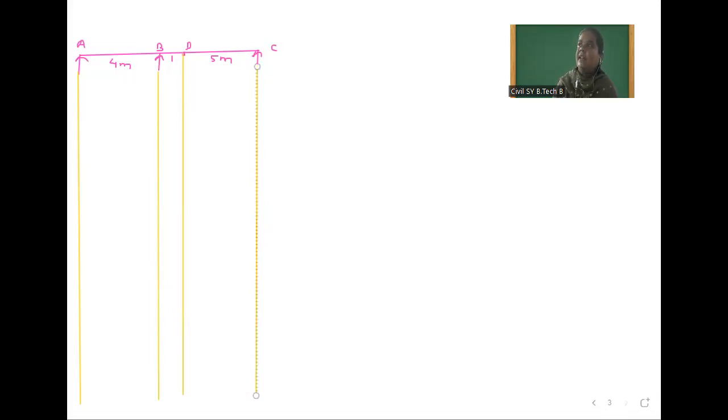First we will draw for RA. So first I will draw here baseline. Suppose this is baseline. Whenever we will draw for A point, at that time one value for this A point. Okay, after that 0 for B. Okay, after that from this B to D, one hinge is provided. So diagram will continue up to D only, and after that here rotation is possible. So diagram will close here like that. Okay, so this is the ILD for RA.